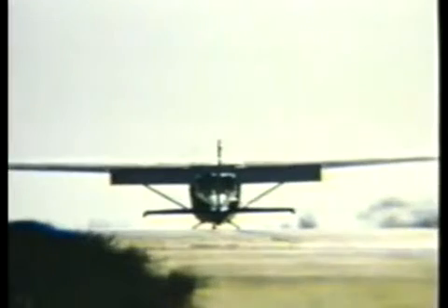If you've been flying for a while, you've probably experienced that strange sensation associated with landing up or down an incline. FAA utility airport design standards allow maximum grades of up to 2%, or about 1.2 degrees of slope. At such airports, runway slope is a comparatively minor factor.